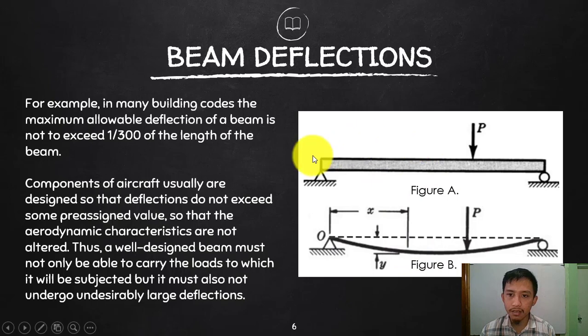Of course, due to the movement of live load, because of this big deflection there will be a big vertical vibration, and that will cause discomfort within the crowd utilizing the facility. So it is important for us to investigate also the deflections, not just the capacity of the beam, but also the deflections, for serviceability.